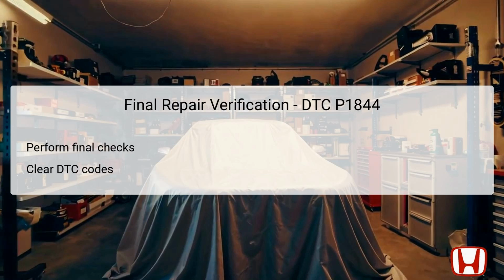After all diagnostics and potential repairs have been completed, it's crucial to carry out final verification checks. This involves examining the functionality of both the CVT drive pulley speed sensor and the TCM to ensure that they are operating correctly. Use a scan tool to clear any DTCs that were previously logged. This will allow you to reset the system and monitor for any reemergence of issues.